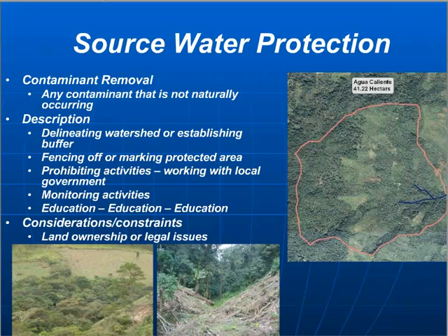This next one is for surface water, and I guess the spring boxes could be surface water, but usually it's groundwater fed. In any case, one thing I wanted to take a second to focus on is that it's not just the hard infrastructure, the concrete work, that is part of the development of that source option. It's also essential to think about the protection of that source area. And so what does that mean for a spring or a surface water source?